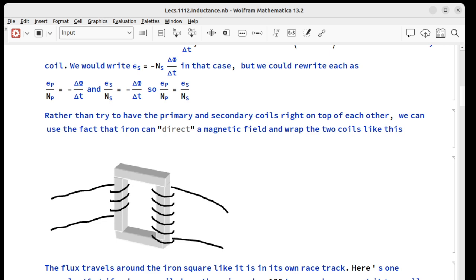This is actually what's powering your doorbell. They all have doorbell transformers that are about the size of your fist, and they bring 120 volts down to 12 volts, or in some cases 18, depending on the doorbell.